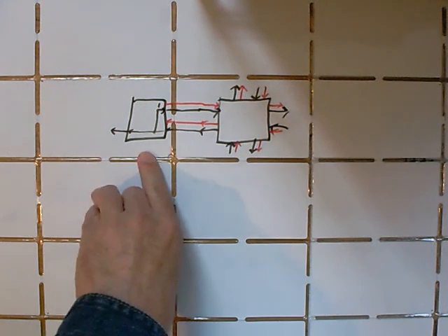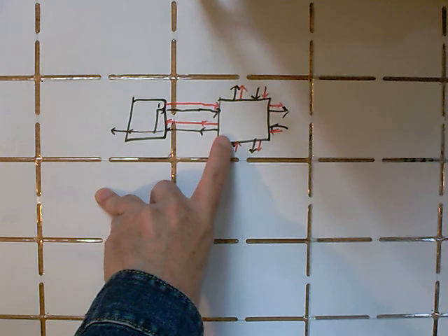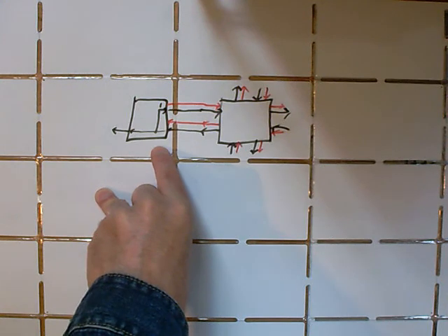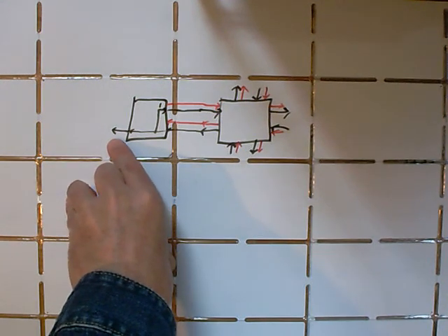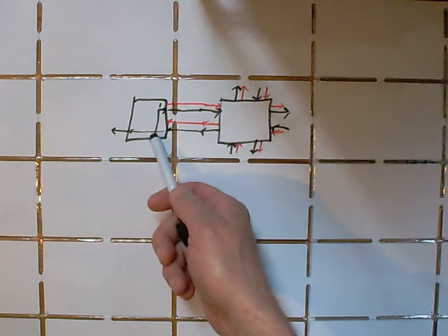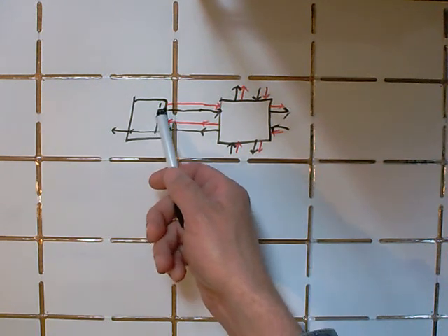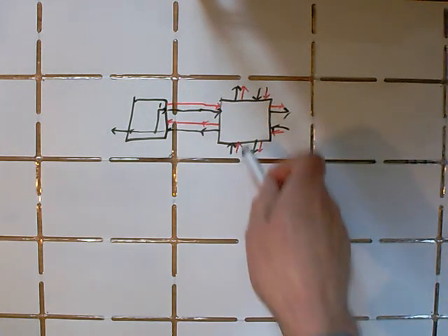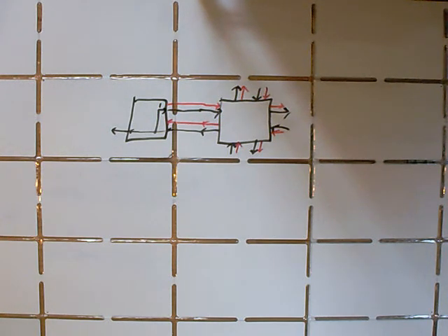So if this cell, which we call the controller, takes the D input from the target cell and resends it back into the D input of the target cell, in addition to sending a copy of that bit stream out to the west, it's now doing a non-destructive read on this cell. So as the system clock ticks, bits from this cell's truth table are sent out into this controller. The controller copies them back into the D input. And the way the timing is set up, this happens in a way that causes the truth table in this target cell to not be disturbed. In other words, the bits are sent out before the new bits coming in need to be available. And so this is a non-destructive read. We take a copy of this cell's truth table and we send it out to the west.